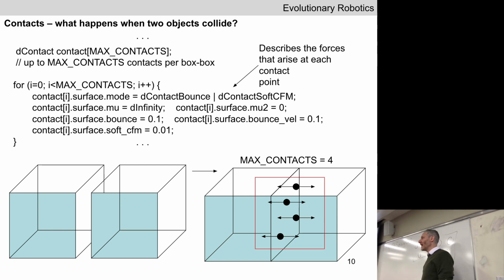When you run the simulation, you don't see it, right? It looks like smooth motion, but like old-timey movies, there's actually discrete frames. It's your eye that's tricking you into thinking that there's continuous motion. In the physics engine, there isn't. Which means, as Nate mentioned, you can have objects that are at time step t just separated, but at time step t+1, they are now overlapping by some amount.